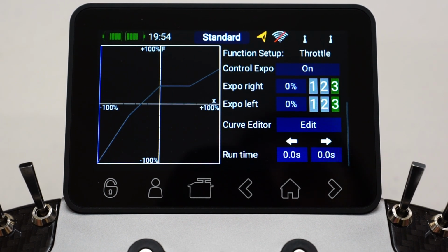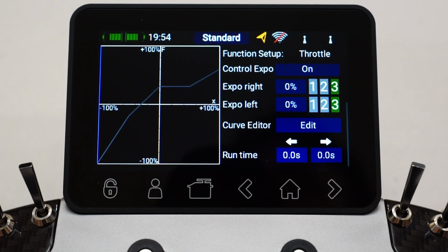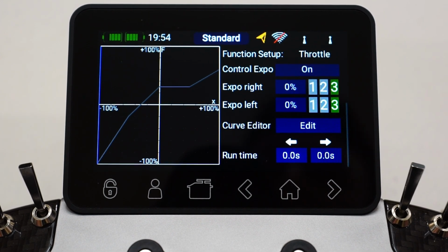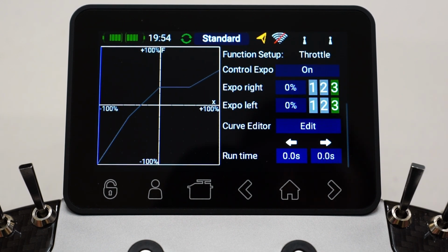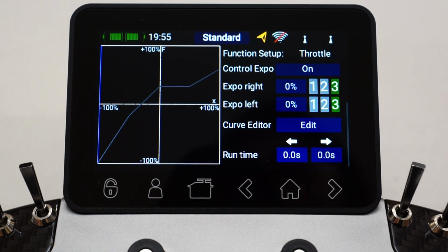I know some pilots, when they do certain maneuvers, push, say, the aileron elevator stick to a corner, and they can activate another flight mode for a particular maneuver. You can also enable that with and without a switch. So you flick a switch, and before that, your aileron elevator stick, if you push it to the corner, doesn't do anything. However, after you flick the switch, if you move the stick into the corner, you can then activate a particular flight mode. So that's handy for selecting different parameters.